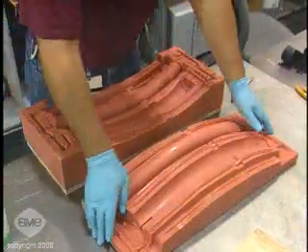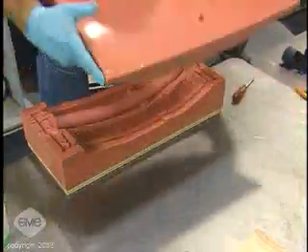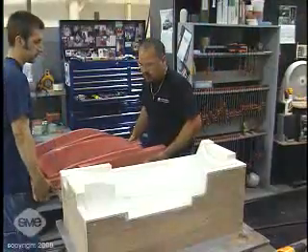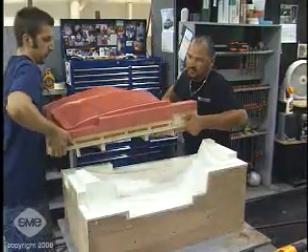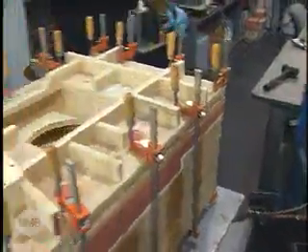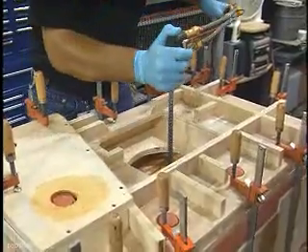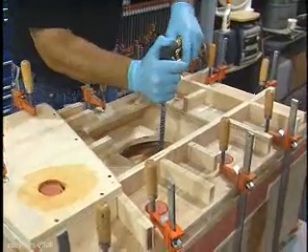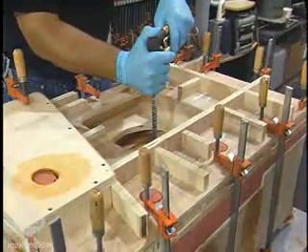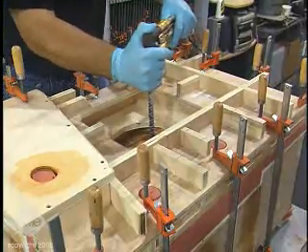Dozens of simple parts can be produced from a single silicone rubber mold, but 10 to 20 is typical if the parts are more complex. Wear of the mold occurs due to the exothermic and reactive nature of the molding materials, and because of the necessity to mechanically deform the mold to remove parts.